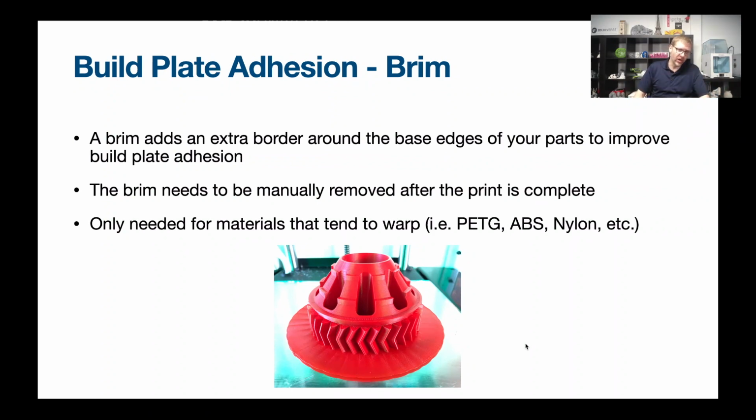And when it's done printing and you take it off the build plate, you have to remove that brim, and you might need to go around with an X-Acto knife or something to trim the extra bits that are left behind. So there's a little bit of extra work involved, but not much. And it's a very reliable way of improving adhesion. But I will say, using some of the advanced adhesives we'll talk about in a short while, even this I usually find is not necessary.